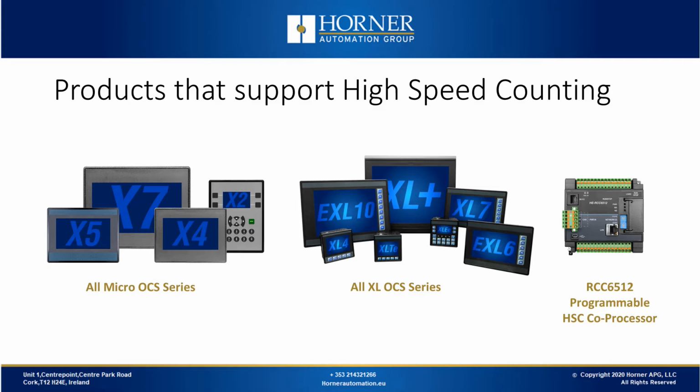Our XL series OCS also does a very good job with high-speed counting. We also have an RCC 6512, a programmable high-speed counter coprocessor. It doesn't just count, it also provides a variety of advanced counting functions, and has a very flexible means of interfacing over a variety of networks, Ethernet, CAN, etc. It also has some built-in logic capability to do logic remotely. It's typically used with other OCS products. It doesn't need to be, but the amount of local logic is limited, which I'll talk about later.